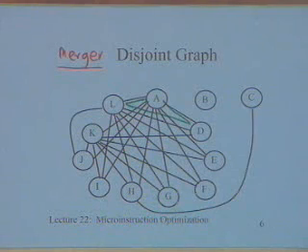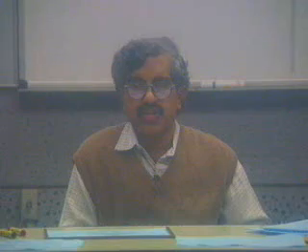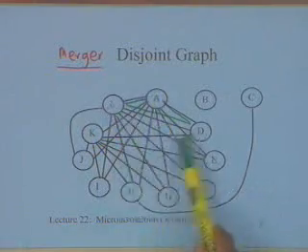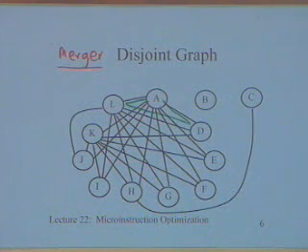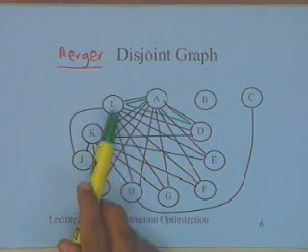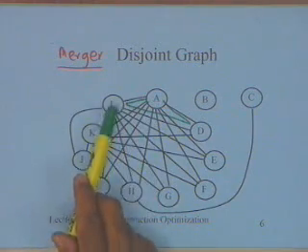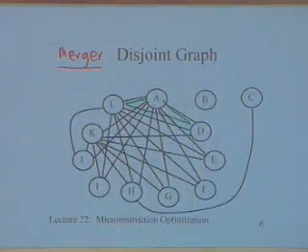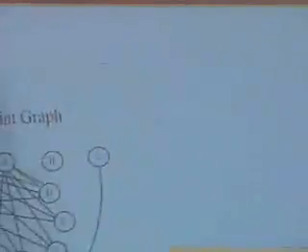There are of course many cliques, but we want to identify a set of cliques, and because we are doing a partitioning, all the nodes should be covered by one clique, and the same node should not be present in more than one clique. Each of these cliques is going to map onto one field. If I say that A, D and L is one clique and I make a field out of it, that means that particular field will contain control signals for A, D as well as L. And that can occur because they are disjoint. So there will be no control step where both A and L are active, no control step where both D and L are active, and no control step where both A and D are active. So I can generate this.